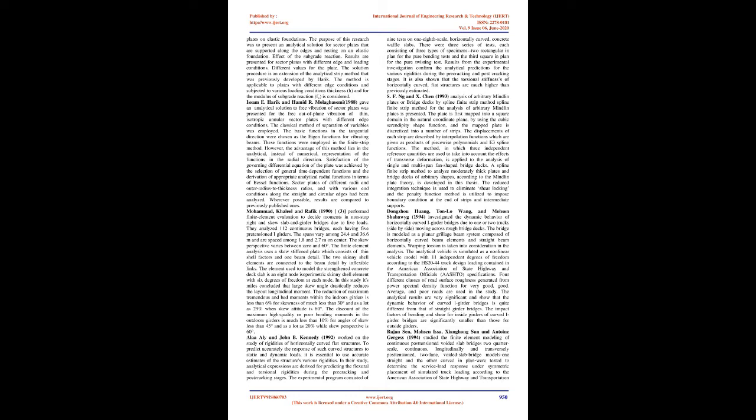A spline finite strip method to analyze moderately thick plates and bridge decks of arbitrary shapes, according to the Mindlin plate theory, is developed in this thesis. The reduced integration technique is used to eliminate shear locking, and the penalty function method is utilized to impose boundary conditions at the ends of strips and intermediate supports.